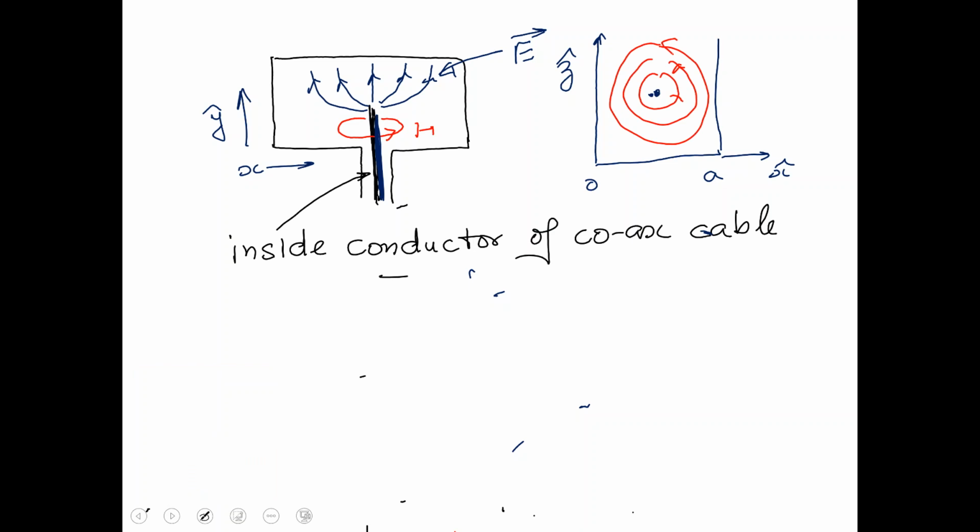And you would notice that this field is roughly the same shape as the TE10 mode. For TE10 mode, the magnetic field is making loops in the Z direction and then it is propagating forward. At certain places the loops are positive, and at other places the loops are negative. So this is the way you can excite a TE10 mode.